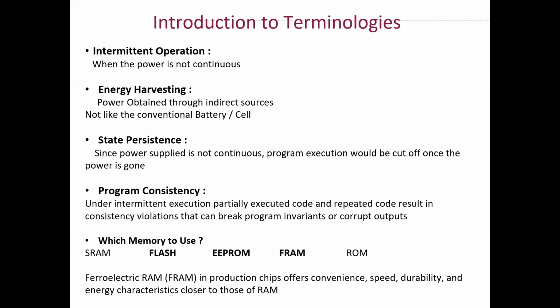The next thing is state persistence. Since the power supply is not continuous, your program execution is going to be halted as soon as it loses power. State persistence refers to the ability of a system or application to retain and remember its current state or data even after it has been shut down or restarted. In computing terms, state refers to the collection of data that represents the current condition or configuration of a program. This includes variables, settings, registers, any interrupt settings, or any such information.